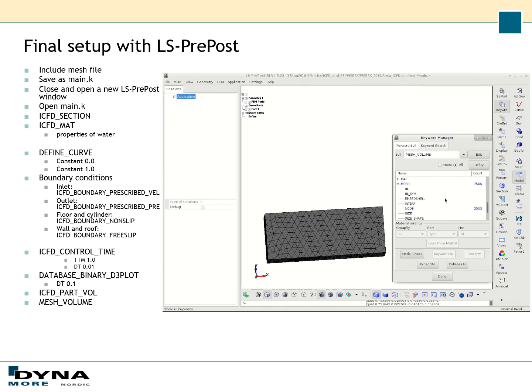If you like, you can also specify boundary layers on some surfaces. You can specify mesh refinements in certain regions, but here we will leave that as default.